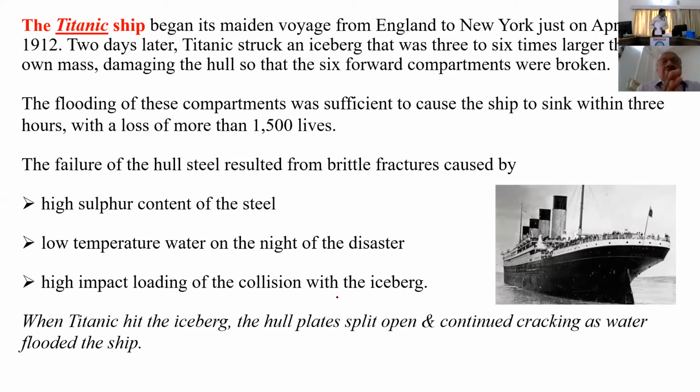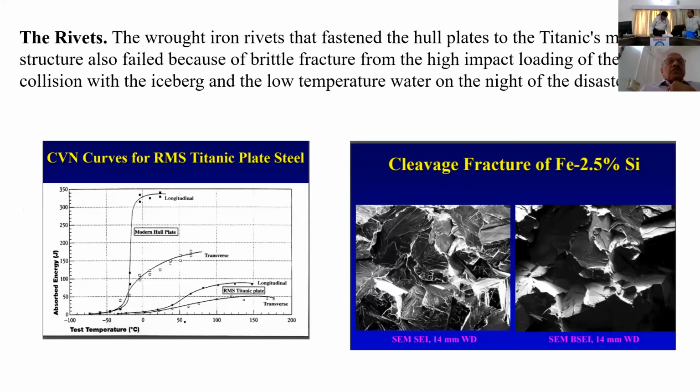So when Titanic hit the iceberg, the hull plates simply split open and the crack propagated and the ship sank. So people took the parts and studied the impact properties. What you see here is the impact curve of the material taken from that Titanic ship.